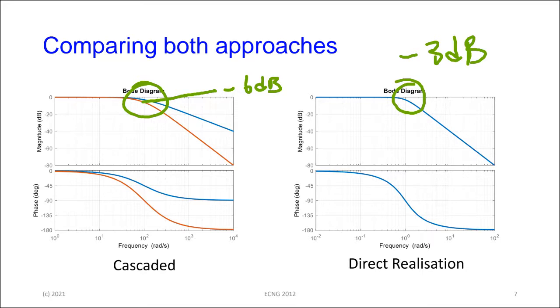This is a very subtle sort of point, but if you think about filtering very small, low-level signals, that could probably make the difference between the signal passing through and not, right? It's twice the attenuation. So you have to look at it that way. 3 dB looks like a small thing on a log scale, but remember 3 dB is 0.707 of what the passband value is, 70%.